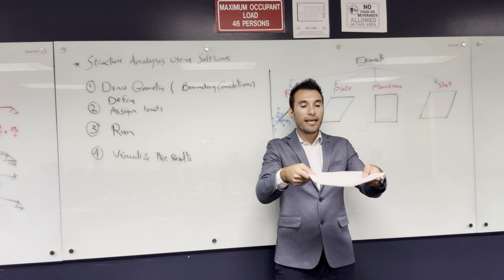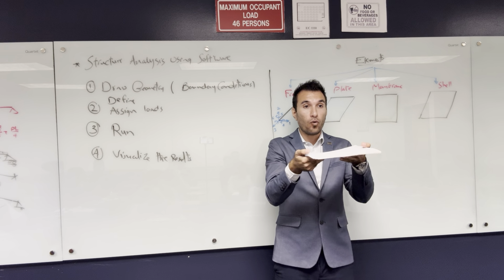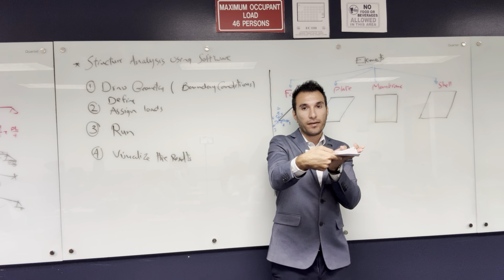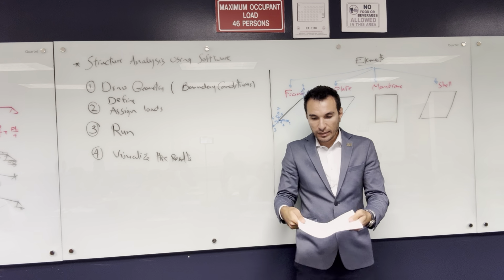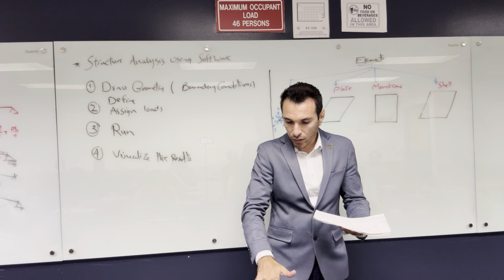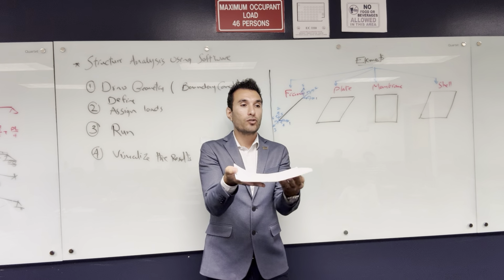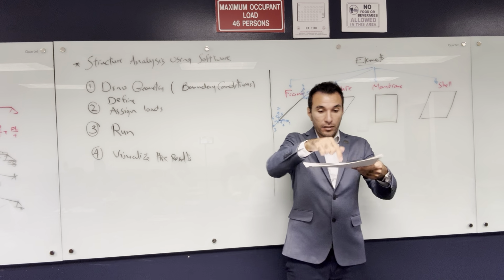And it can deform downward, but it cannot move X and cannot move Y, and cannot have a torsion that way. So this slab that we are in can bend this way because of our load. Once we put the load this way, it's gonna bend that way. And it's a two-way slab, so it's gonna have two-way moment. And there's a deformation in the middle.